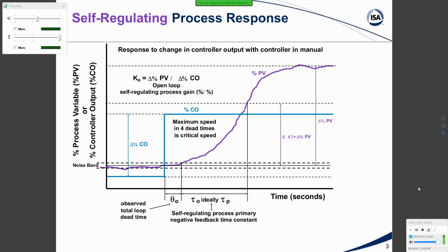Now, a second order response would try and identify the second largest time constant as well. If the largest time constant in the loop is greater than 4 times the dead time, it is classified as near integrating. And I didn't realize how important this was until I started to look at tuning loops, particularly using lambda tuning. Bilkowski, like 10, 20 years ago, did mention this, but he didn't say when you needed to do this switch to a near integrating process.